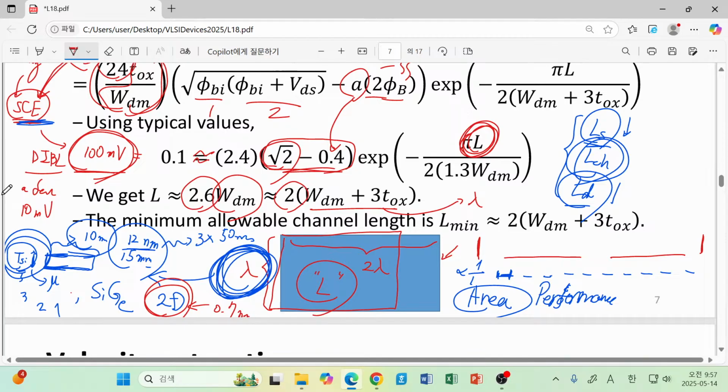So even though we introduce a 0.7 nanometer thin channel, its mobility is more or less its own mobility. But I have to say that actually they don't have a quite high mobility. So it's not that good a material in terms of current conditions, but they do not degrade significantly.